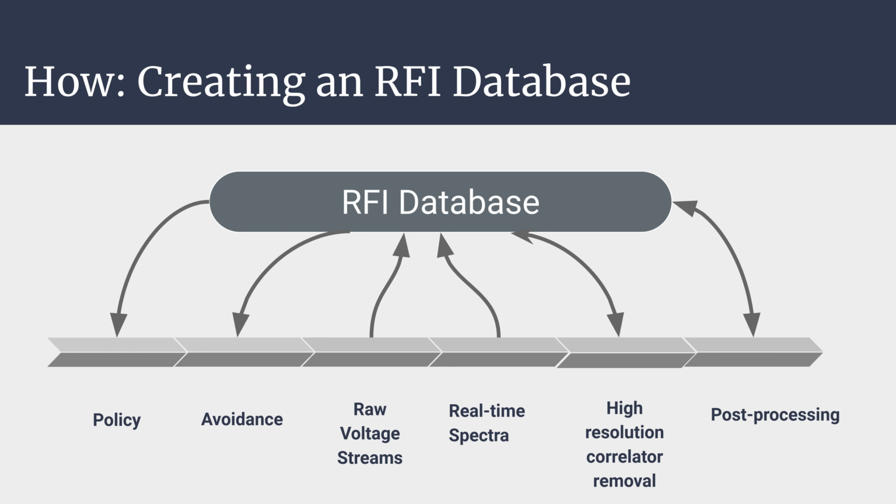It'll answer the question of whether the RFI environment is suitable for high resolution flagging in the correlator. Like, is there enough space between duty cycles for usable data to warrant high resolution flagging? Currently, that's unknown. And then metadata would support developing algorithms that model and subtract RFI, so one could potentially recover sky signals from underneath RFI. And by keeping metadata at individual antennas, we can better study the amount of decorrelation that's happening in processing.